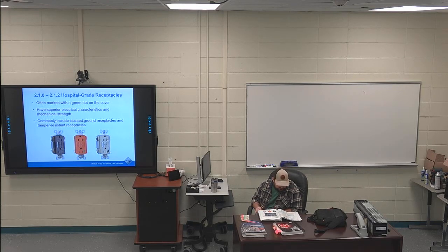It is difficult to prevent a conductive path from a grounded object to a patient's body in a healthcare facility. The path may be created accidentally or through instruments directly connected to the patient that act as a source of electrical current. This hazard worsens as more equipment is used near a patient, such as in surgical suites and intensive care units. The more you connect to a patient, the higher the chance they are grounded, and you have to make sure they're not going to get shocked.